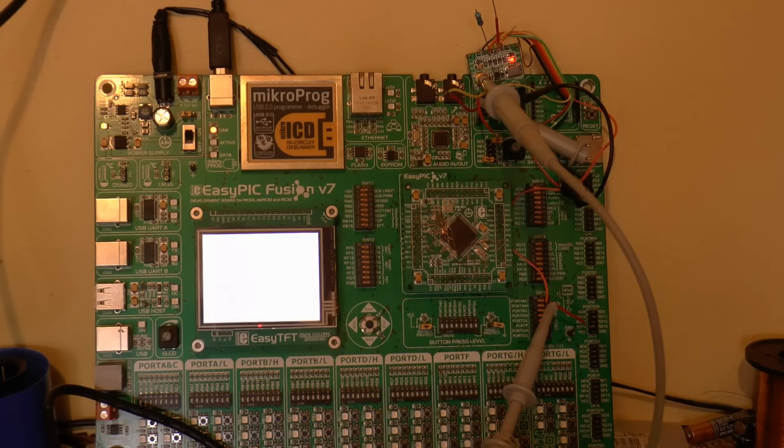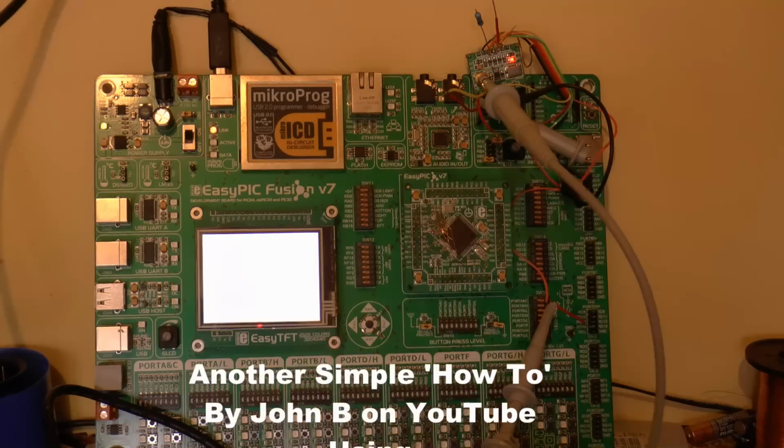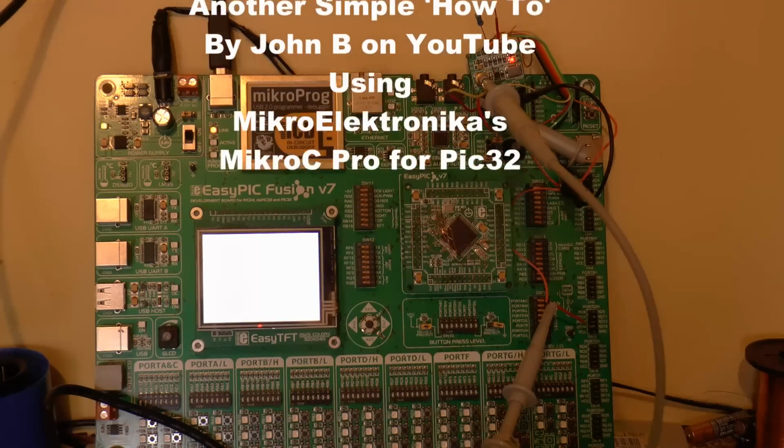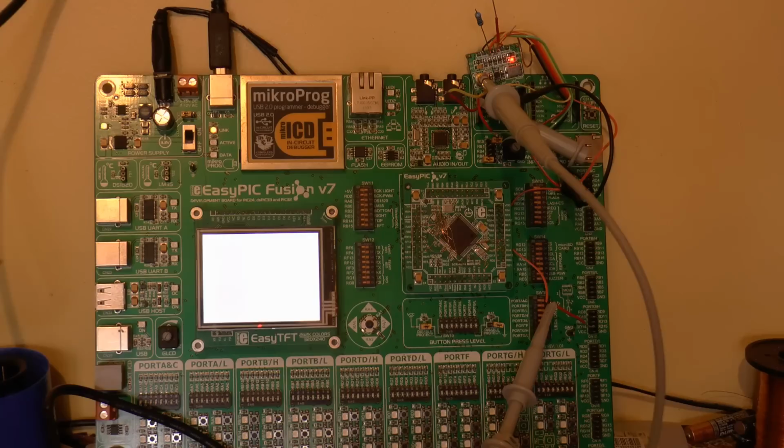Hopefully this has helped. It's taken me days to understand why a simple chip, simple communication wouldn't work. Had a look at loads of forums, seems loads of other people are struggling, and it seems to be down to that frame select. If the frame select turns off too slowly, the chip won't always update. Hopefully this has helped. Thank you very much.